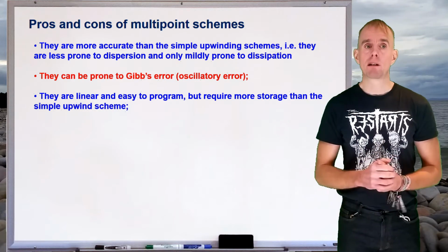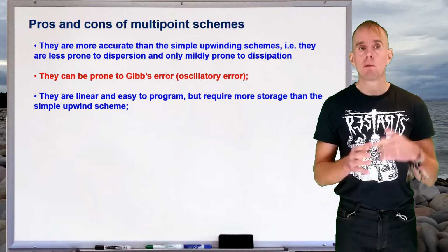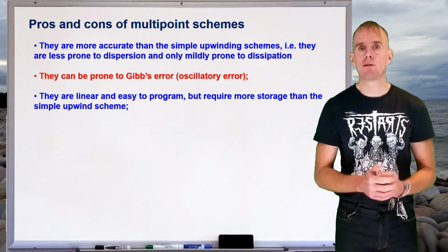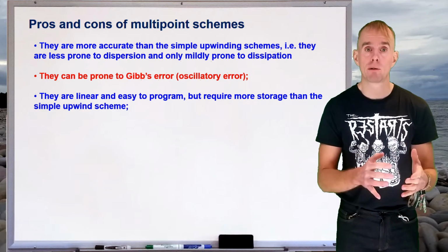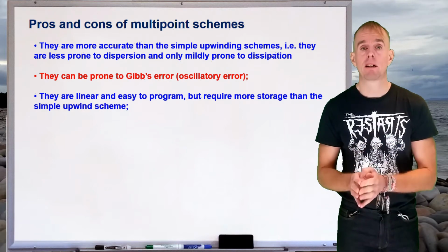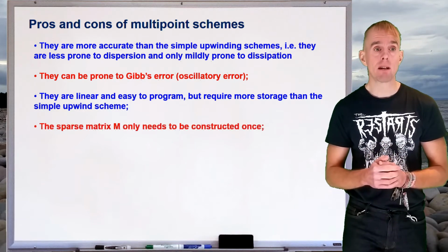These solutions are programmed up in MATLAB for a point of reference, but the thing to remember is that when you're using multi-point schemes, they do need more storage space in memory. And so depending on the scale of the problem you're solving, you might want to look quite critically at how much RAM you've actually got on the computer that you're using.